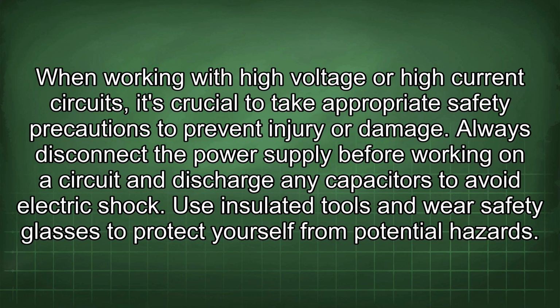When working with high voltage or high current circuits, it's crucial to take appropriate safety precautions to prevent injury or damage. Always disconnect the power supply before working on a circuit and discharge any capacitors to avoid electric shock. Use insulated tools and wear safety glasses to protect yourself from potential hazards.